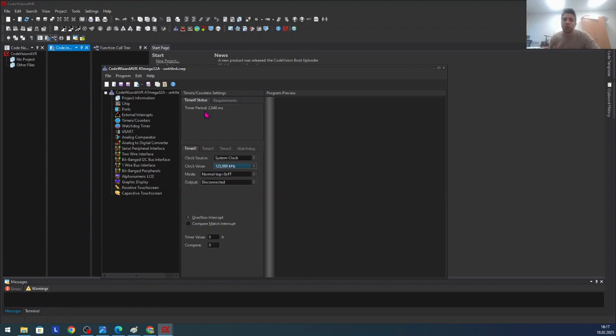It's okay if we use that, it will work, but we want to adjust to 4. So I want to show how you do that. Then we choose the higher prescaler value, so we use the lower frequency of the clock. If we use this, it means it takes 8 milliseconds for the counter to count from 0 to 255.